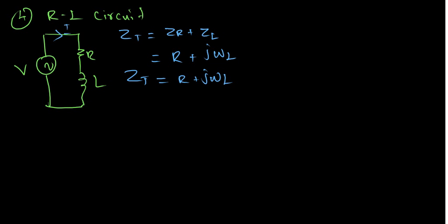This is the important part. How we start the phasor diagram is, what is the common part of the circuit? Usually in series, the current is the common part. So I'm starting with the current I. There is a voltage VR and a VL here. So how do we start VR? VR is not leading or lagging the current. So I start VR.